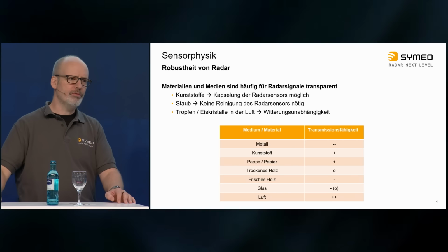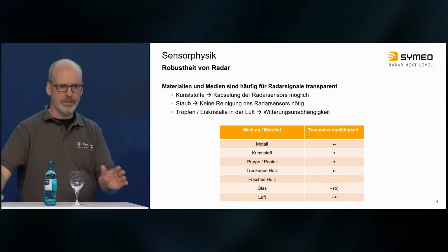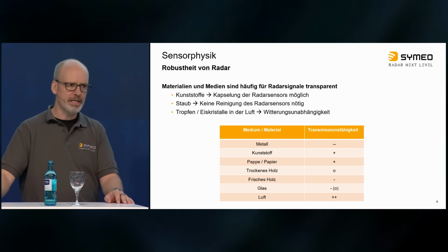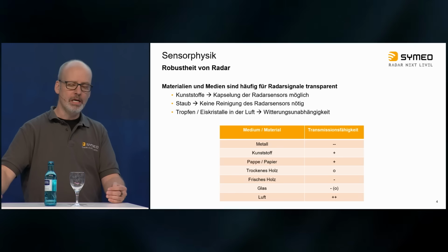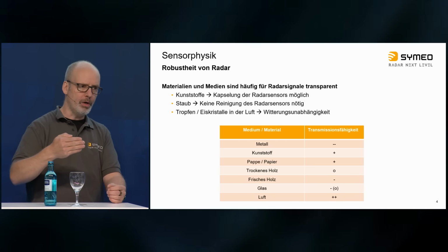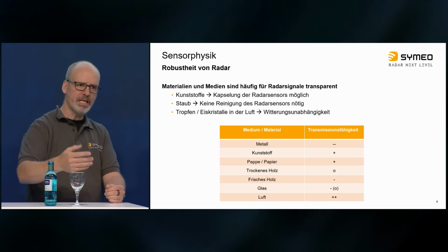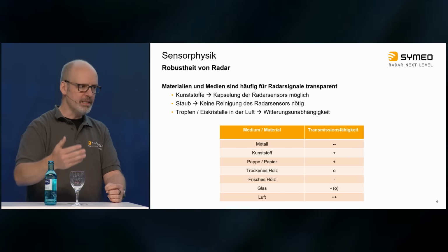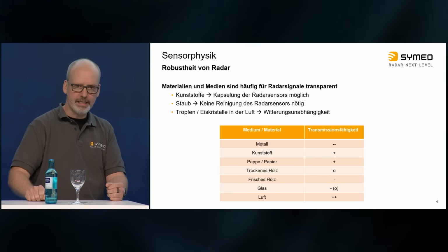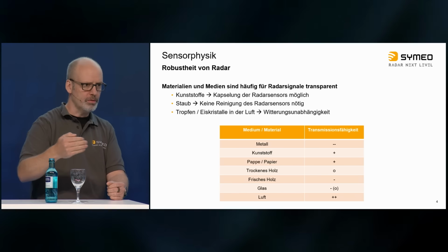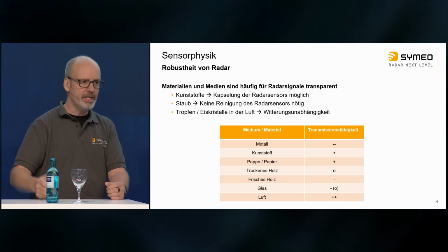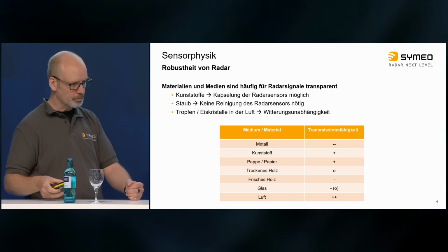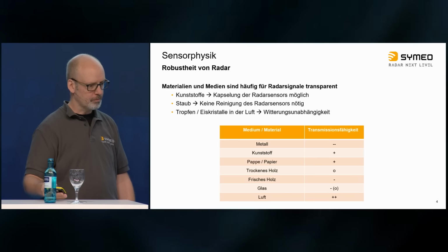In the middle range, there's also material like wood, dry wood, thin wood. That's great, hardly visible on the radar. Moist wood can be a target. For instance, in the wood industry, if I look at the sliced wood and there's some residual moisture, I can identify it as a target, and I can position the wood log if I need that in the wood industry.